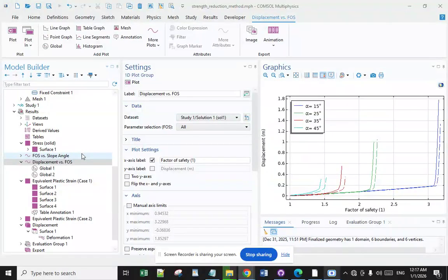For loading that is cyclical, repetitive, or fluctuating, it is important to consider the possibility of metal fatigue when choosing a factor of safety. A cyclic load well below a material's yield strength can cause failure if it is repeated through enough cycling.